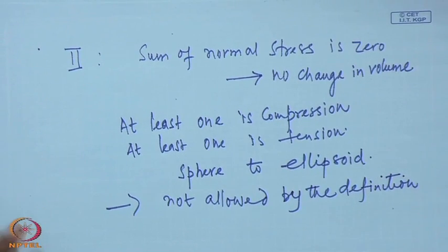So, what is the meaning of this then? That when a fluid is at rest, the stress system has to be isotropic, equal in all direction, and as it happens this is compression, and all axis systems are principal axis systems.